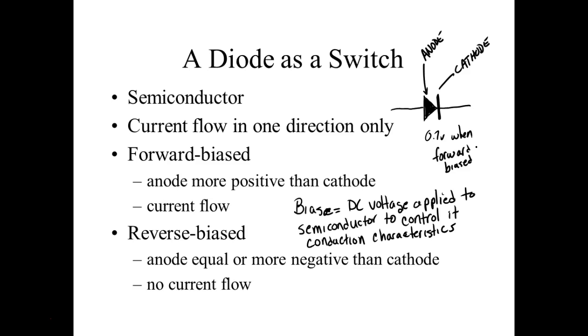So follow me so far. This is the guy that converts AC to DC. You run into these all over. We have an alternator on your car, but your car is a DC system. So they've got what they call rectifier banks. They're rectifiers, and they're nothing but a bunch of diodes that only let that AC run in one direction, which would give us DC, right? You understand?